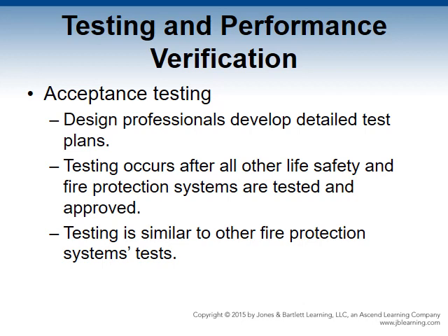Acceptance testing. The design professional developed a detailed testing plan that provides a description of the smoke control system, the design criteria, and how they will be demonstrated and proven, what will constitute a successful performance, and a step-by-step procedure, the test instrument and equipment to be used. The test usually occurs after all other life safety and fire protection systems have been tested and approved. The smoke management system depends on these other systems. Testing is similar to that of other fire protection systems.